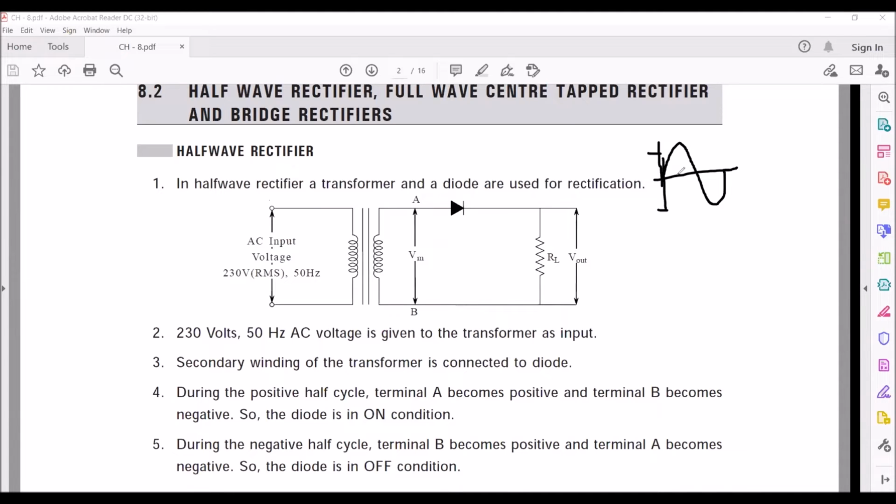We want to perform the average, mean, root mean square. But when we perform the average of this signal, the average will be 0 because we have positive and negative voltages. So we square each and every value and then consider the root. That's why we call this the root mean square value.